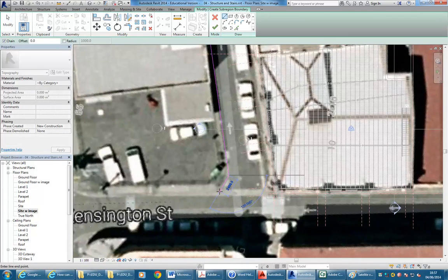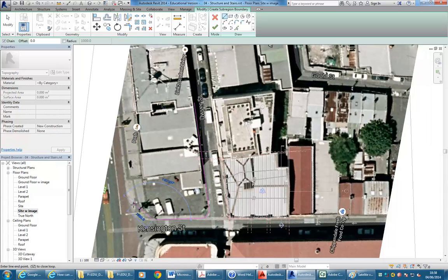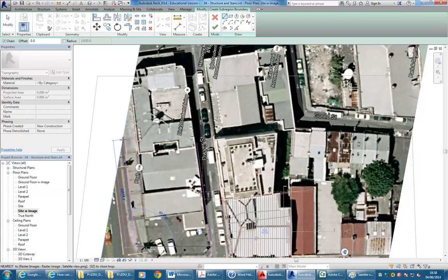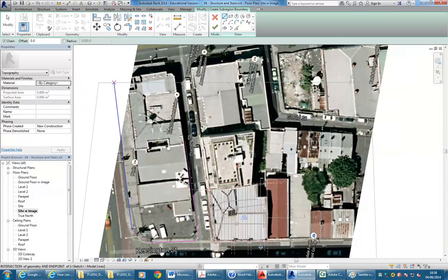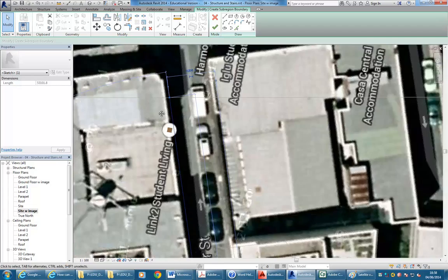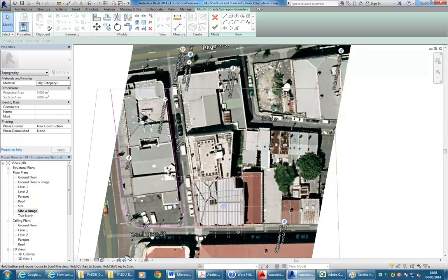Okay, so just with some more lines for the shape I want here, and if you worry about those rounded corners, I'll show you some tricks to get those. Probably know already using fillet arc. Oh, okay, so here I've gotten to the edge of my topo surface. Oh no, so that's the edge of my image. The edge of the topo surface, sorry, is up there, but I do want to go to the edge just so you can see what happens. You don't need to go over the edge, so you just need to go up to it. And then here, it'll be the same. So I can just extend that line up to touch, but not go over. So you don't need to trace over the edge there. And it'll give you an error, actually, if you do.